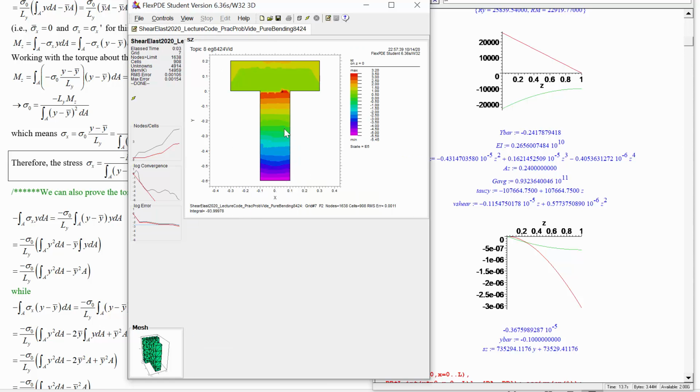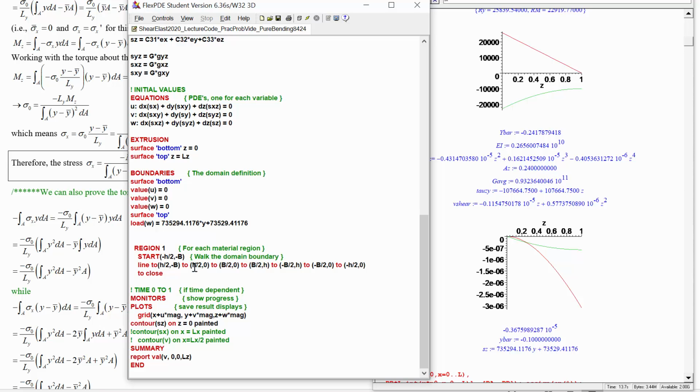Interesting. So most of the stress is taking place in the tungsten. That's because it's a lot stiffer. So you see a lot more of these contour lines going through it. The aluminum ends up with a very similar displacement and not much stress difference across it, like the changes that you have for a given step in the tungsten, because it's so much stiffer. So a little bit of strain difference here makes a lot more difference in stress than the strain difference here does. Okay, so that is something.